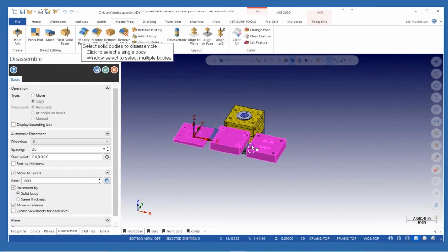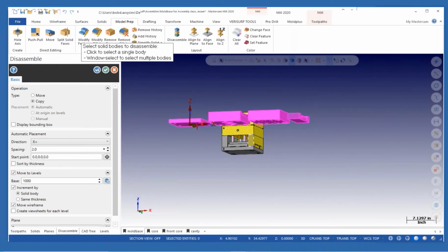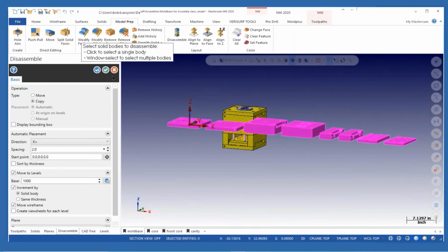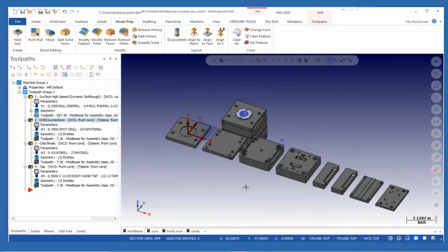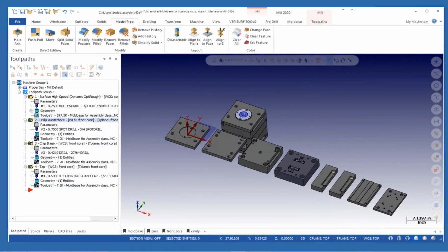again. I can grab the new plates. It's going to put them exactly where it did previously. So my geometry, my containment boundaries, everything that I did in the toolpaths that I have associated with the old geometry is going to be usable in this geometry, and I simply need to regenerate my toolpaths. I don't have to manipulate. All the planes will still be there. It makes this function very, very useful.